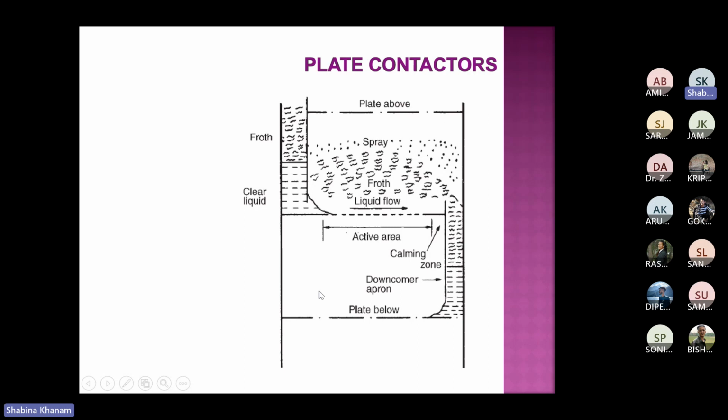Their interaction is not possible, because it passes through the liquid without any interaction, or we can say it makes a hole like a jet and moves upward. That condition is called coning condition. All these points we need to discuss. And as I have told you, before flooding occurs, entrainment occurs.